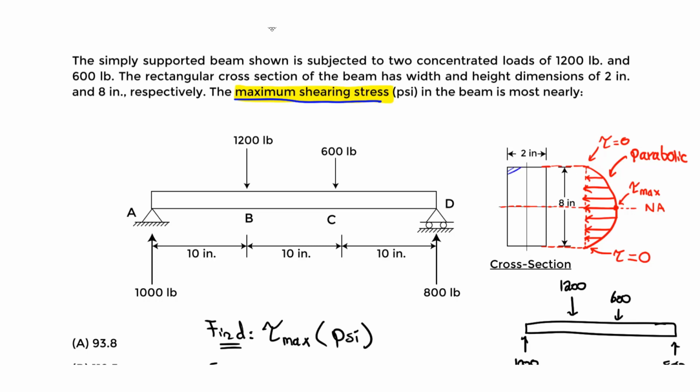Here, I'll just use the one above. It's actually the same in this case. That's going to be the area we look at, and that area is the A prime value. For A prime, you just take the area of that shape. We know the whole thing is 8, so this dimension is 8 divided by 2, which is 4 inches. So the area of this shape is 2 inches times 4 inches, which is 8 inches squared. Now we're done with A prime.